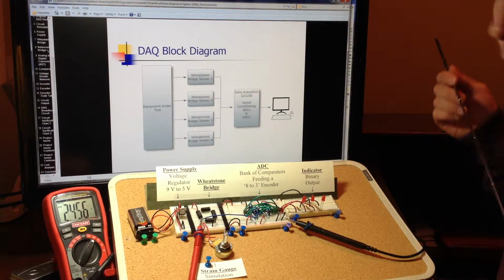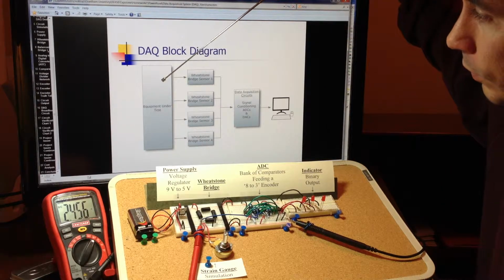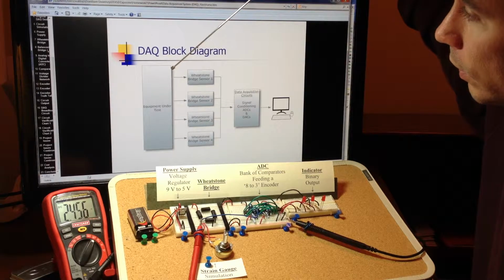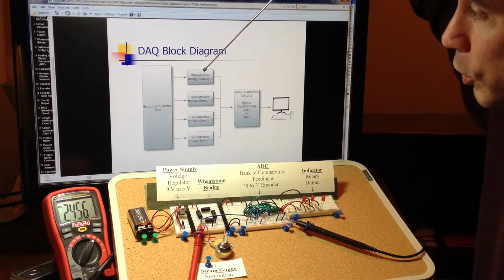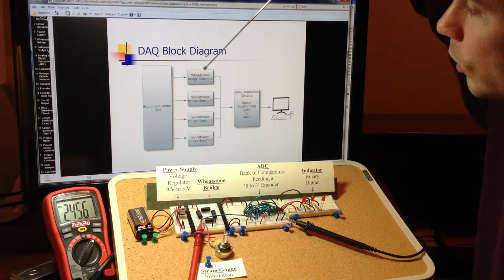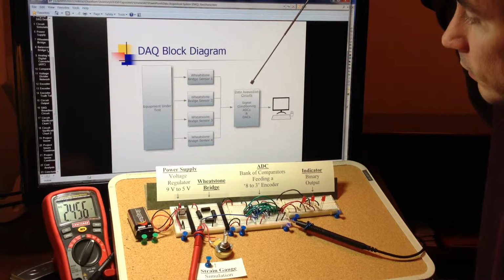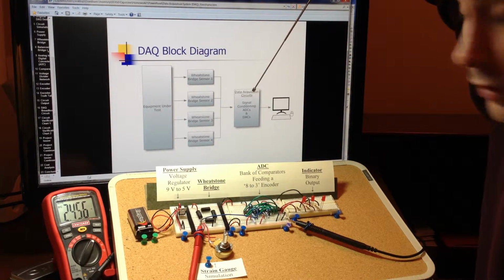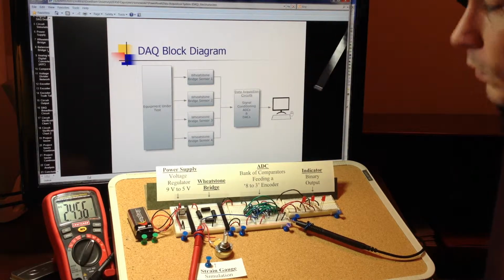This is a block diagram of a data acquisition system. It includes the equipment under test, which when stimulated, exerts a force on the Wheatstone bridge sensors. The Wheatstone bridge sensors then produce a voltage that is seen by the data acquisition circuits. It's signal conditioned and sent off to a personal computer for data analysis.